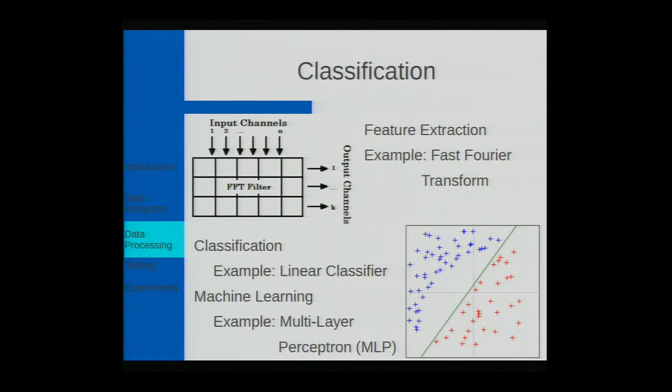This is the example. And here once we have clean data, we have to take it into feature vectors for the classifier. The example here would be a fast Fourier transform where we divide it up by frequency into bins, and then we have those bins over time over sensors, which is a fairly large space, but for certain classifiers, that large space is okay.